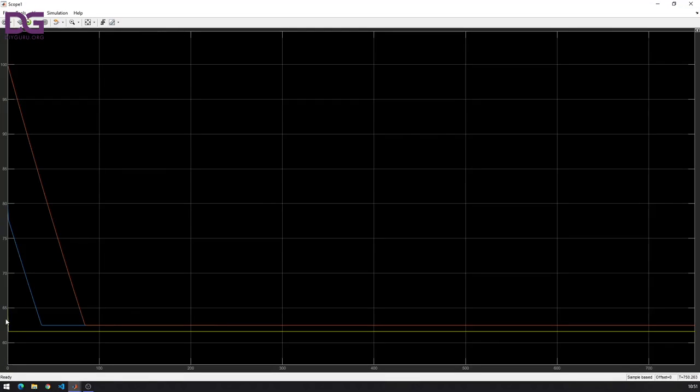You can see here the lowest one was here. Obviously it will dissipate some energy, some SOC, because after the beginning the system will take some charge to evaluate the process, and once it determines that this cell has the lowest SOC available right now, meaning the lowest voltage available, then it will just drop the voltage or the state of charge of other cells so that they can match, and once this cell balancing is complete they can charge again.